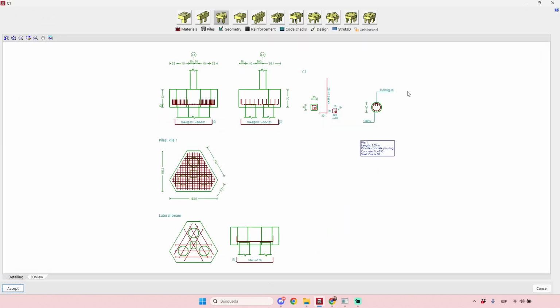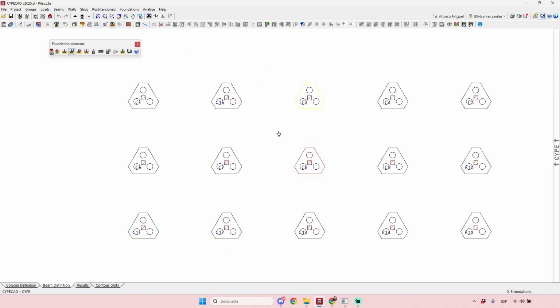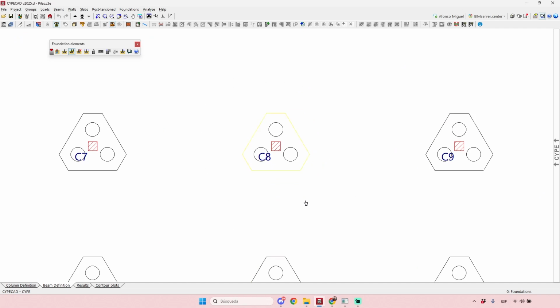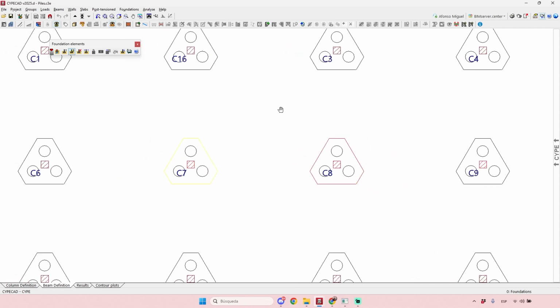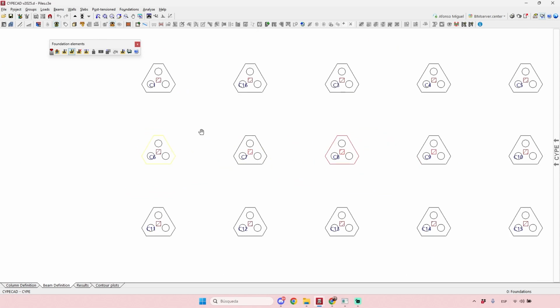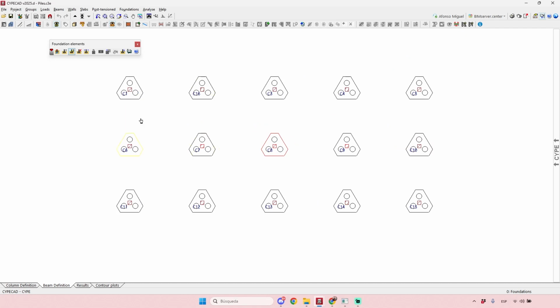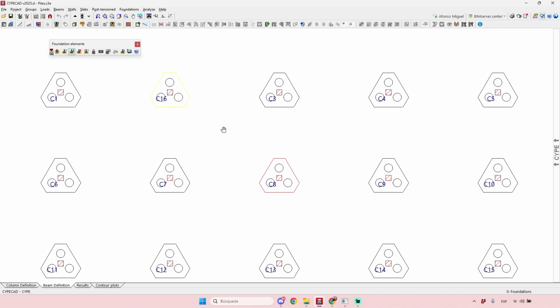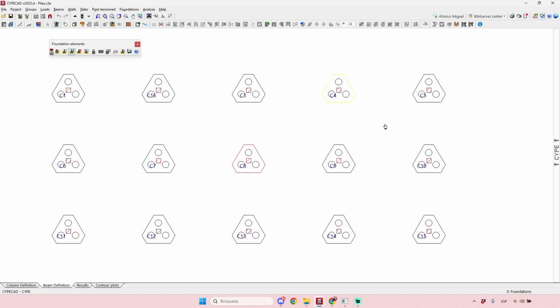Okay. Coming back here to the model, you see that, for example, in some situations, I can have the pile cap in an unsafe situation, as is this case here. So the pile cap is in red color, okay? In some situations we can have the column, like this one, the column is unsafe. Here the column is safe, and we could also have the pile. In this situation, all the piles were safe, but the pile itself could be also in red, and we'll see this graphical representation of the piles in red, meaning that we must check something.